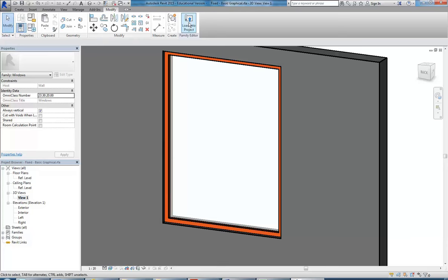Okay, so I've got that going across multiple levels. And I've got these transoms that are obviously, or the floors coming through. And when I bring the floors back, I probably want to have a transom in the window that's going to cover up that floor. So I'm going to show you how you can add in things like that to your family.